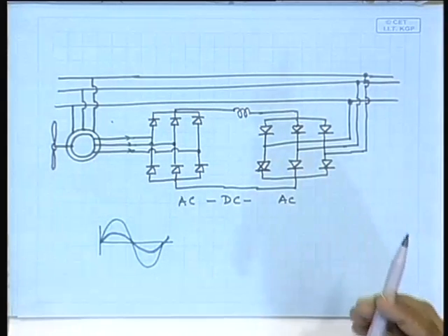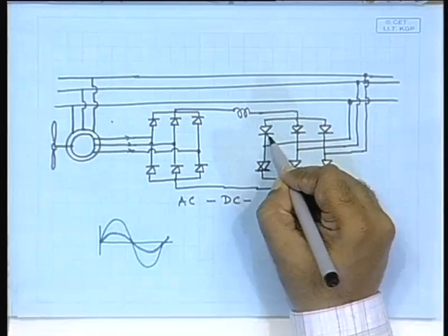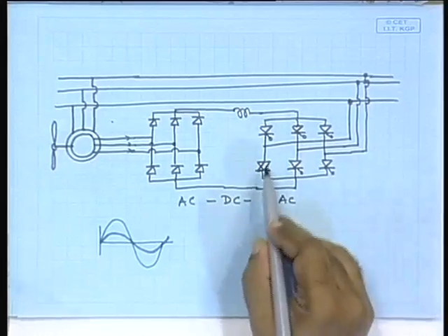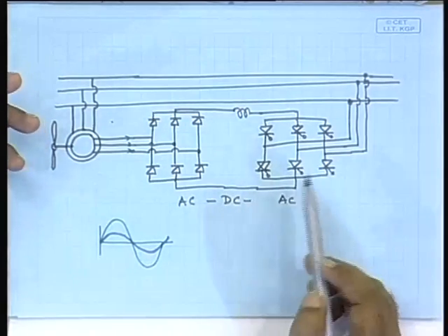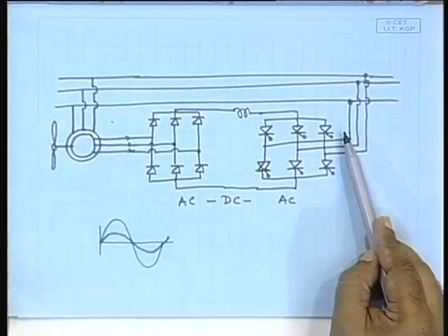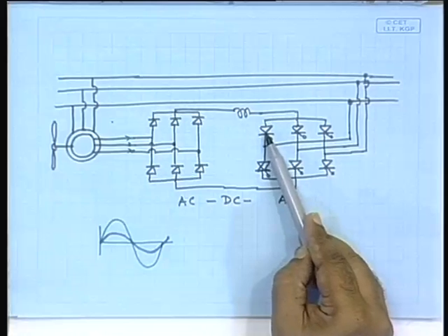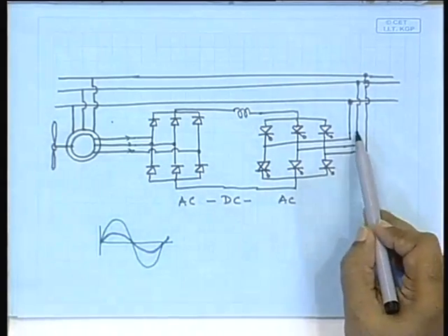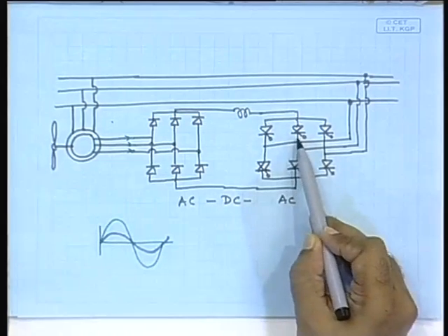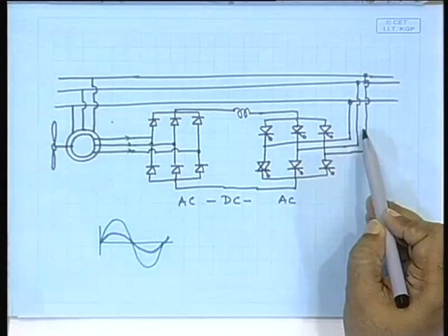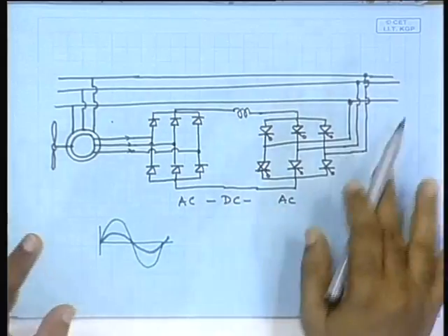Oh, well. Then, oh, I did not draw it correctly. These are all controlled. So, their switching is controlled. For some time you want this voltage to become a positive one. At that point, when you want that, you turn this one on. When you want the next one to be positive, you turn this off and turn this on, and so on and so forth. It is basically choosing the time sequence properly so that a three-phase AC is generated here. But really I cannot go into the details of it.